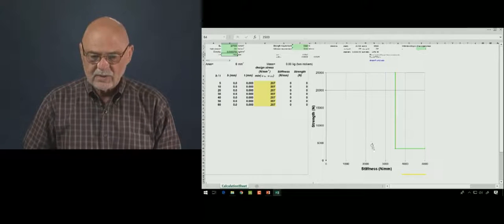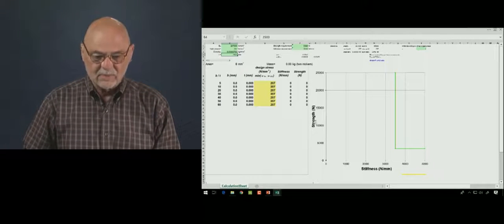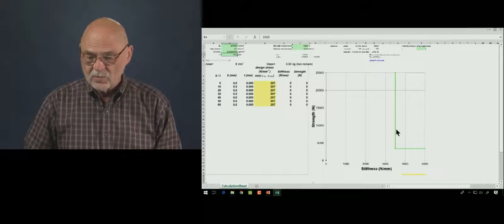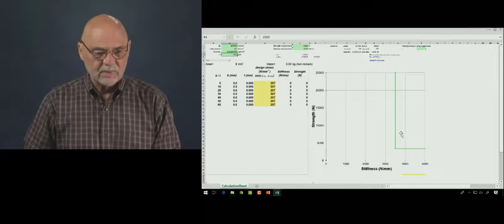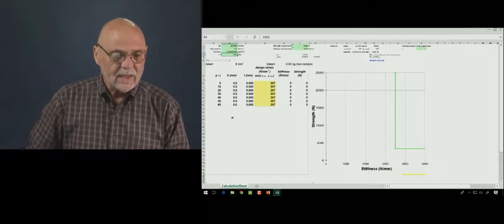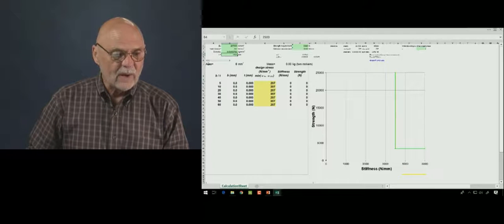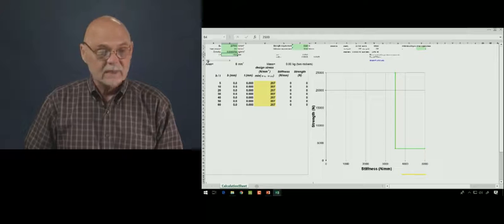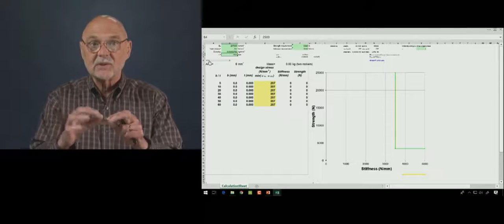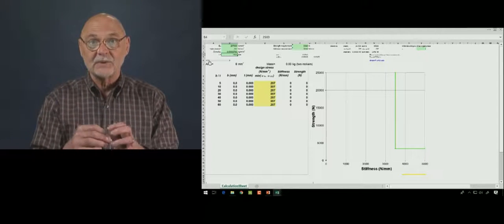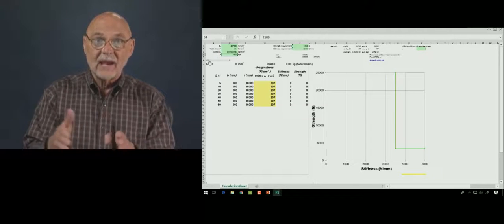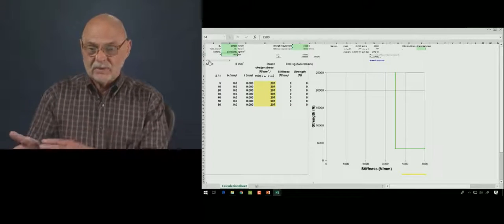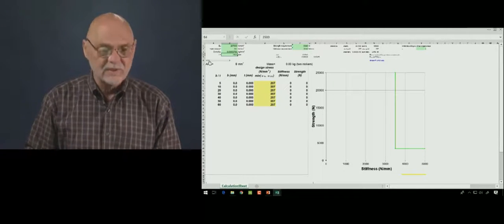So here's a chart that we were looking at before. Here's the beam strength, the stiffness, and here's the region that we're trying to jump into. And here's a little scroll bar, so I can change the cross-sectional area of the beam. Okay? So some beams will just be too skimpy. We just don't have enough material, and we'll have to keep adding material until we get into the region of interest.